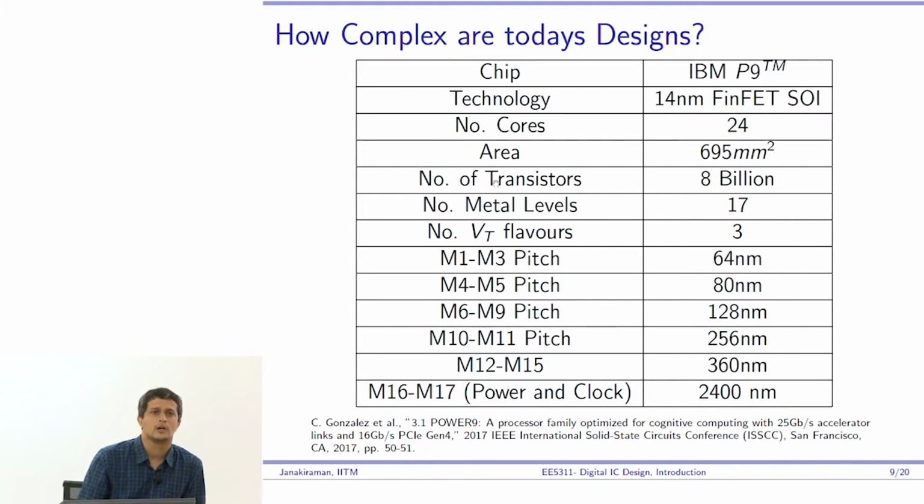Okay, so now if the on current of a transistor is a microamp and the off current, as I told you, is 1000 nanoamp, why is the off current even a cause for concern? It's a nanoamp, right? You have 8 billion of these transistors leaking a nanoamp each, which means very quickly we are just leaking amperes of current, right? And what does leaking mean?